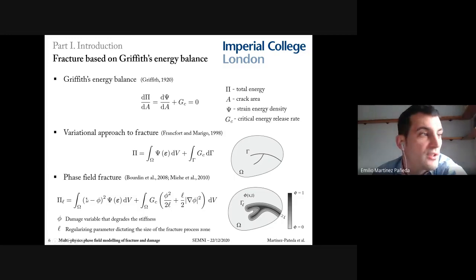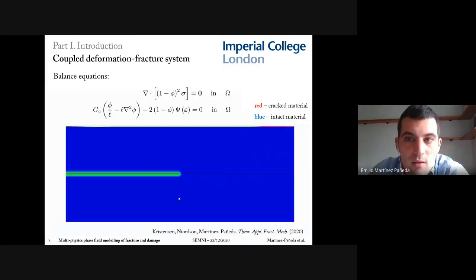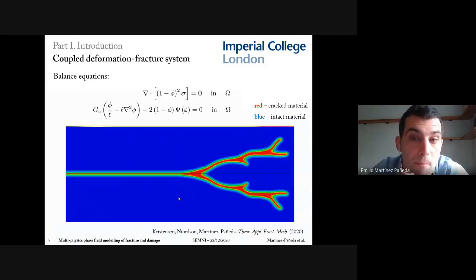You can see that in the first integral here. Secondly, there's a gradient term, and consequently, a length scale. There's a phase field length scale. So the model is non-local, which ensures mesh objectivity. Results are mesh independent as long as this length scale is resolved. So at the end of the day, we have a model that is physically sound, based on Griffith and the thermodynamics of fracture, and at the same time computationally very compelling.